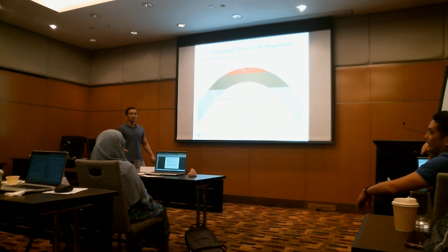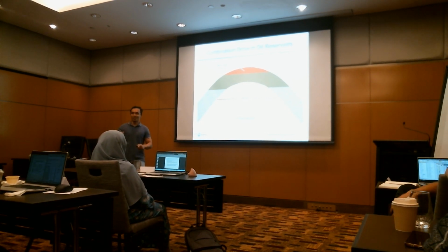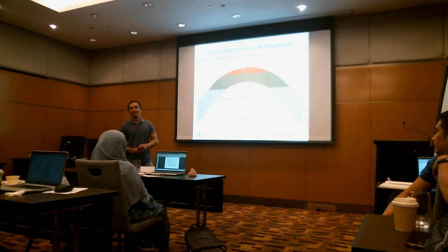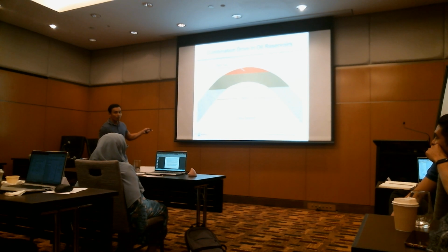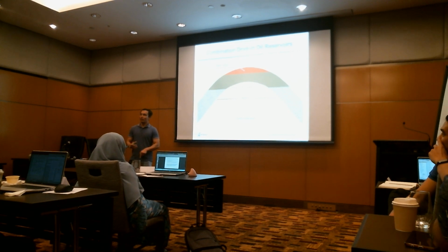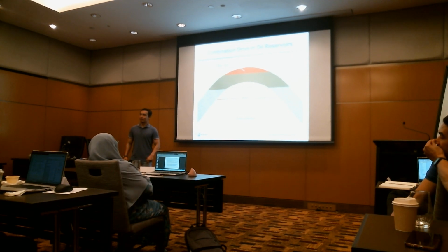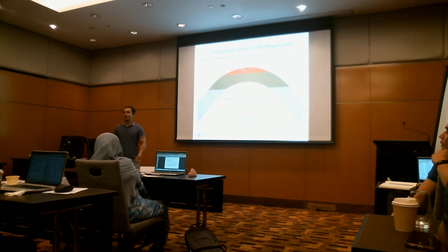One third for gas cap. One third, that's gas. Okay. One third of the oil, halfway. One third of the oil means one third from the gas content, and two thirds to the water. So two thirds from the gas and one third from the water. Why? Because gas is more mobile, so you want to be further away from the gas compared to water.